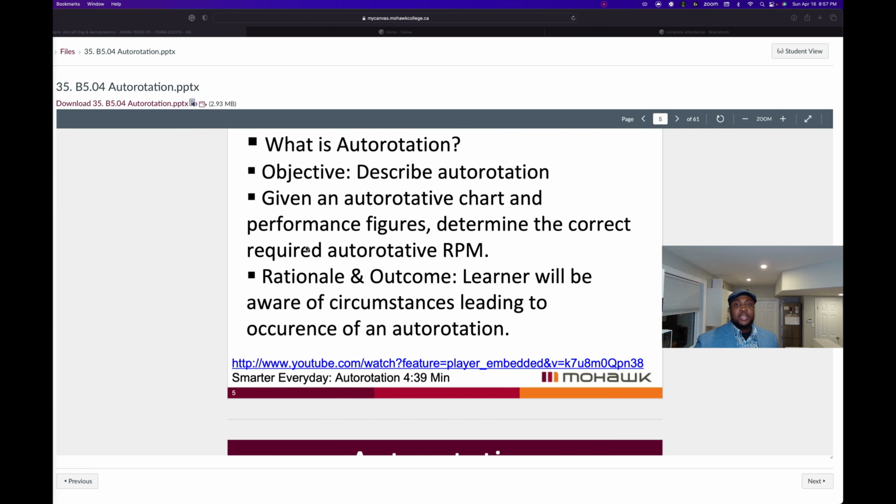So remember that the angle of attack for a given airfoil is the angle between the relative wind and the chord line. This remains true, and this is why it's very advantageous for helicopters to feature a symmetrical blade system or symmetrical airfoil. The total aerodynamic force is increased and has moved forward. As long as rate of descent and rotor RPM stay the same, the helicopter descends at a constant rate.